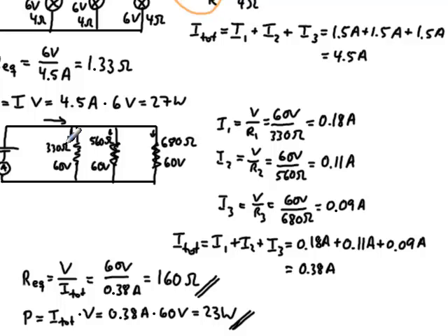This means the overall resistance of the circuit is less than the resistance of any of the branches, or in other words, the equivalent resistance is less than the smallest resistance. So it has to be less than 330, and indeed I came up with 160. However, how do you put 330, 560, and 680 together in order to come up with 160?